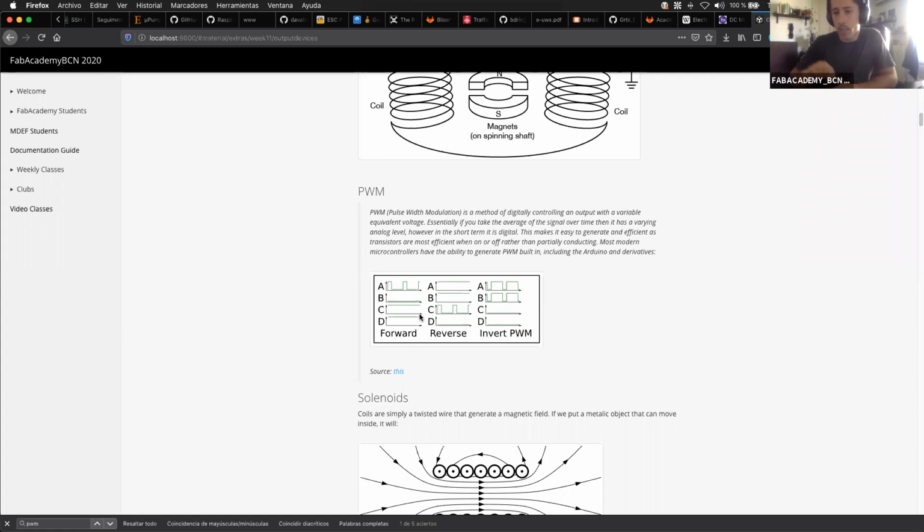Of course, if we do that very slowly, our system will notice and will turn on and off all the time. But if we do it fast enough, and by enough we are talking about hundreds of kilohertz or faster, then we will have an average voltage that is perceived to be almost continuous, but at a lower level than the high voltage or the low voltage.